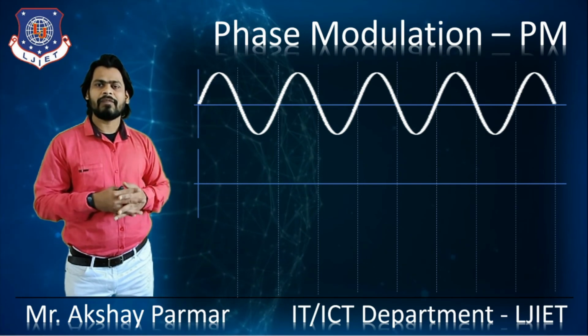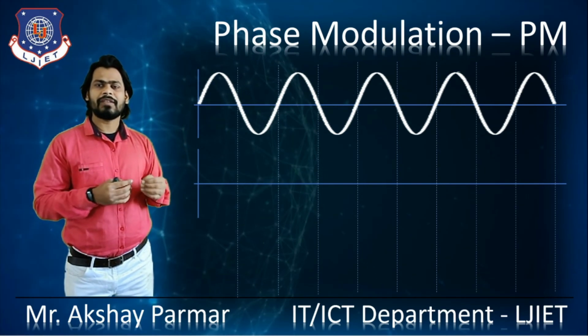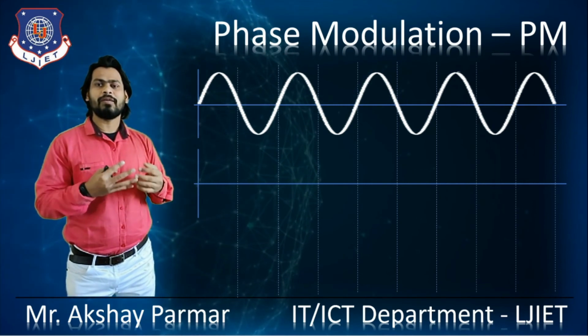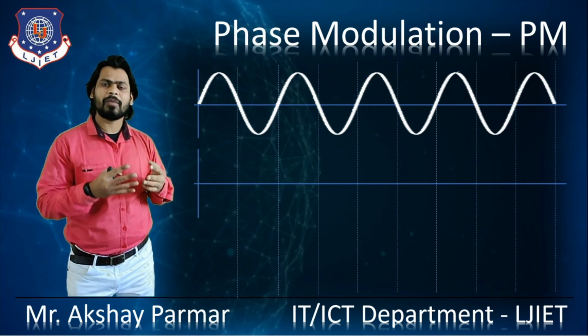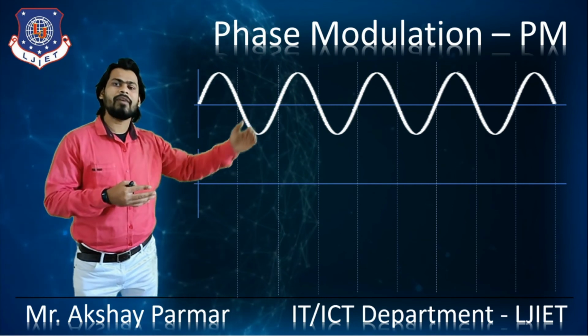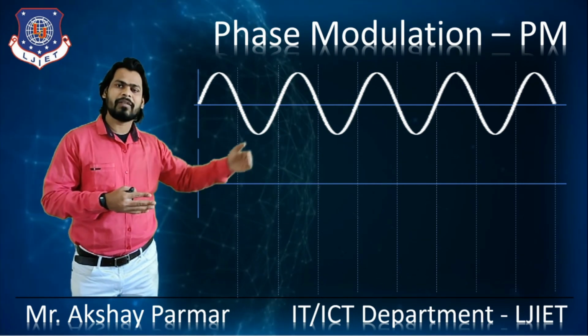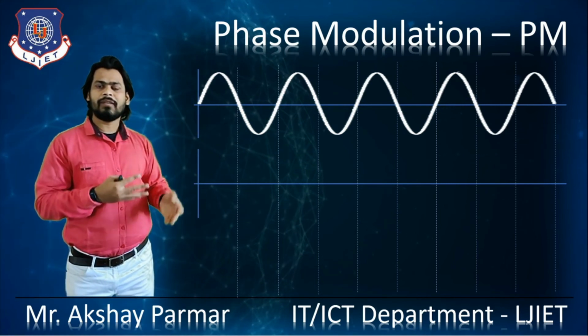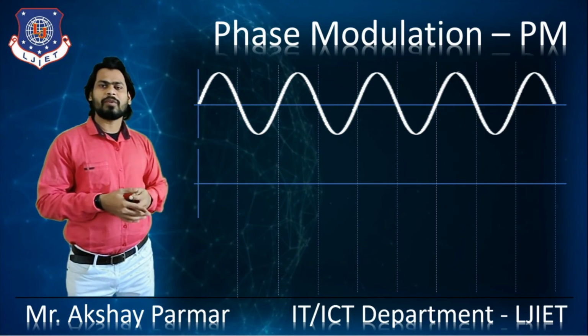In our technique, we have used a 0 degree phase difference to represent the positive side of the signal, and a 180-degree phase difference to represent the negative side of the signal, right? That's how we represent the input signal with phase modulation.